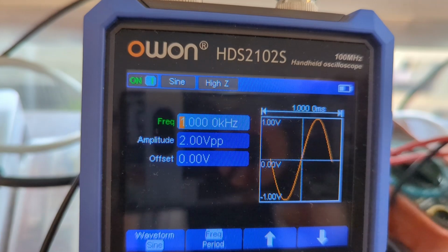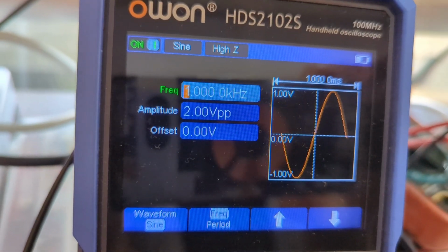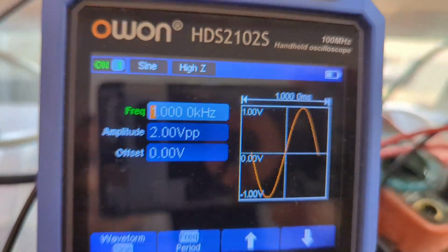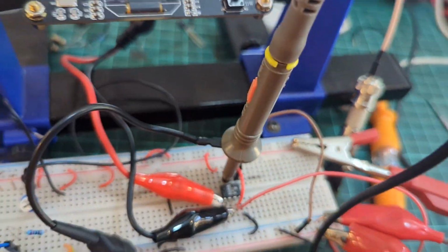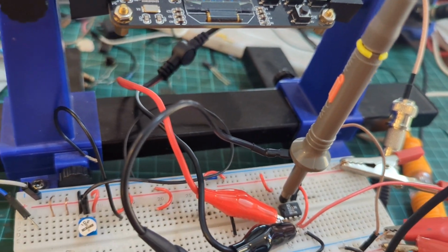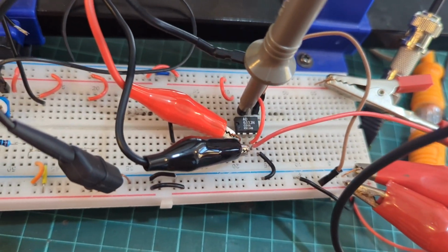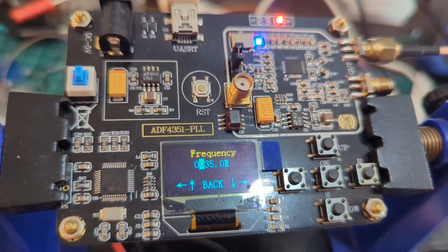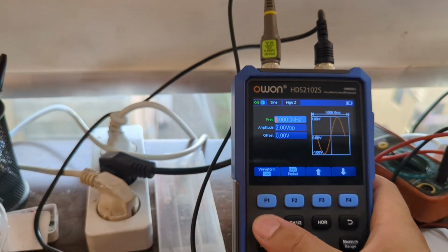So basically up to 30 times larger than the oscilloscope signal. So that's going to be injected into the chip, and what we have is for the modulation input, the signal that, like my voice for example, that's going to come from the oscilloscope, which is 1 megahertz, and the carrier signal is going to be 35 megahertz. So as a result, we will get this.